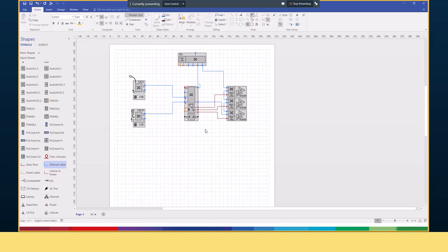So here we have the connection for the network. We have a loop here back to the controller for the amplifier and the MPS. And we have power connection here. Now, why is this loop, that you recognize that, so important? You know about hop count, and you know that you cannot have more than 22 hops in a loop. And here you see, the system controller is 1, 2, 3, 4, 5. So this is a loop of 5 hops, no problem.